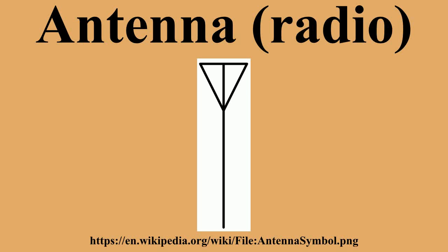For non-directional portable use, a short vertical antenna or a small loop antenna works well, with the main design challenge being that of impedance matching. With a vertical antenna, a loading coil at the base of the antenna may be employed to cancel the reactive component of impedance. Small loop antennas are tuned with parallel capacitors for this purpose.